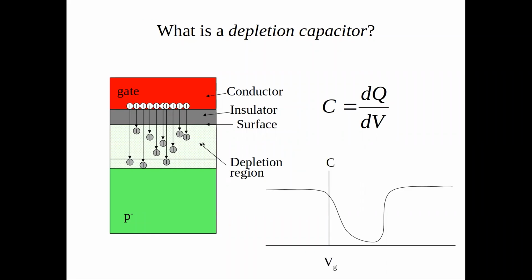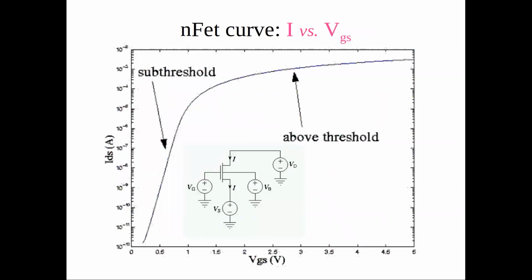Yes. So practically speaking, how come the curve of current doesn't go down? Basically, when you pass the threshold, why does it still increase the intensity as a factor of gate voltage if you have electrons which are being attracted into the depletion region? Are you talking about this current? Yes. Why does the current not go down when you go in strong inversion?